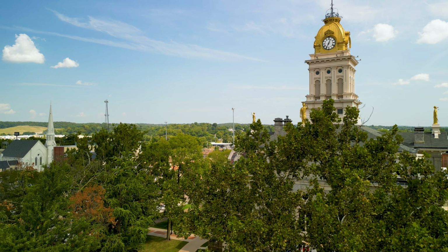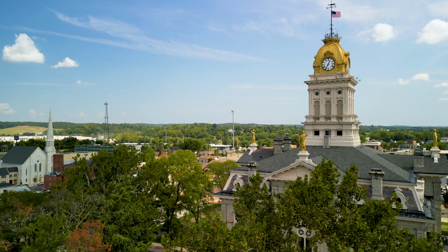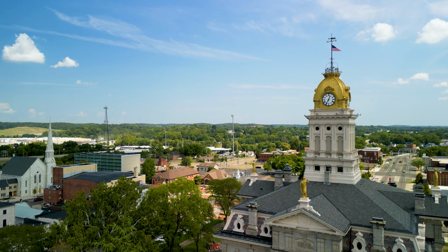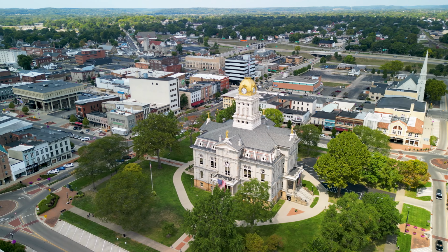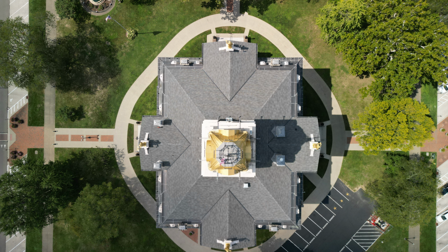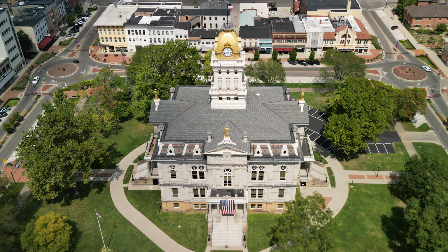To understand why oblique imagery is so effective in 3D modeling, let's consider how photogrammetry works. The software reconstructs a 3D model based on what it sees in the images. For example, when viewing a building facade, a nadir image taken directly from above captures only a thin sliver of pixels on the vertical surface. In contrast, an oblique image taken at an angle captures far more detail on the facade.